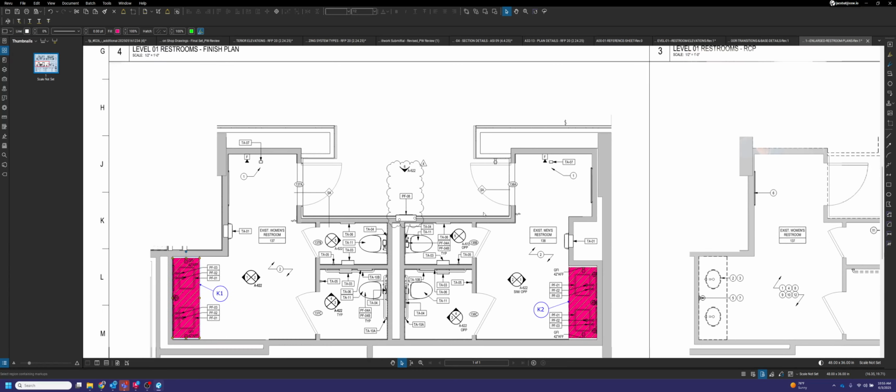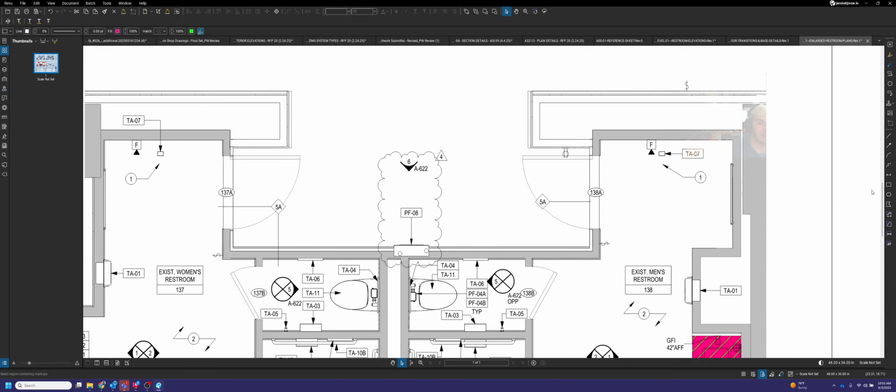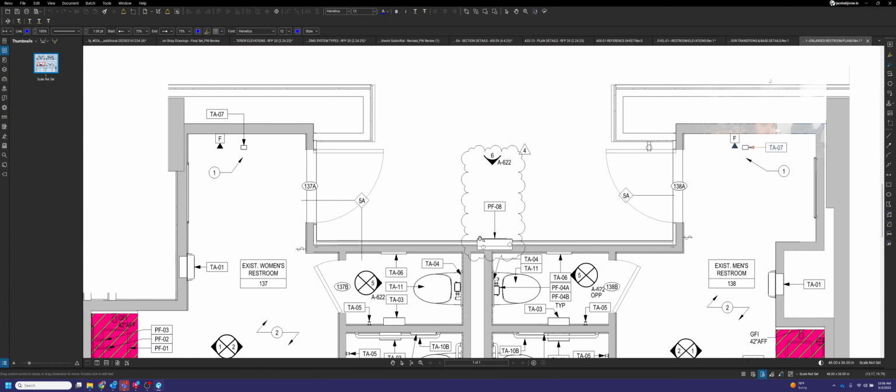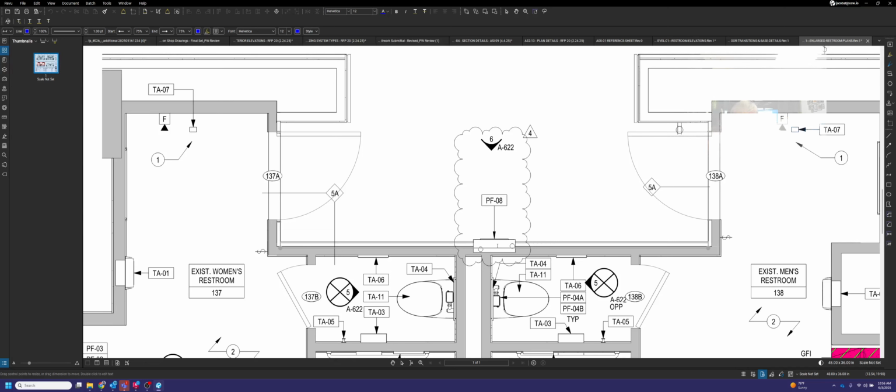So what we're probably going to end up doing is taking the floor plan and importing it into AutoCAD and then scaling it up to full scale to get a general idea of how wide these panels will be from wall to wall. That will likely vary by the time it gets installed. And why I say that is because when walls are framed, there's a chance that they may not be framed to the exact size that they're shown on the print. So when we do go to draw these in, we're going to be using a VIF, or verify in field, dimension here for those. And that's going to span from wall to wall.